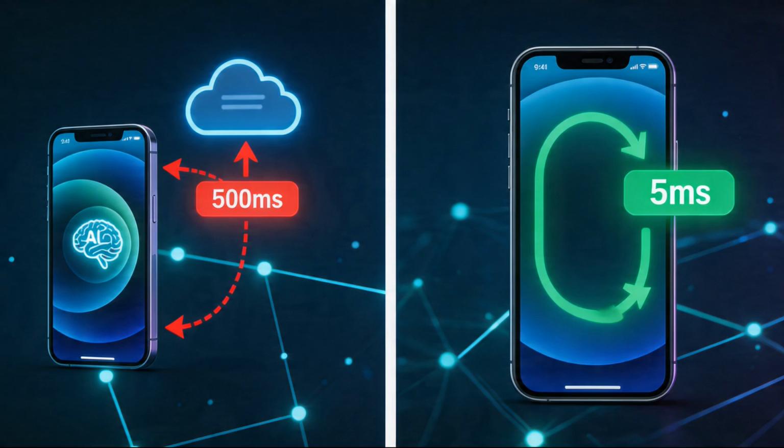For microcontrollers, Edge Impulse is the fastest path. It handles the full pipeline: data collection, training, quantization, and deployment through a browser-based interface. The key design principle for Edge AI: model size is everything. Start with a model under 10 MB. Quantize it. Test on your target hardware early. The performance profile on a Jetson and a Raspberry Pi are dramatically different. Don't assume, measure.